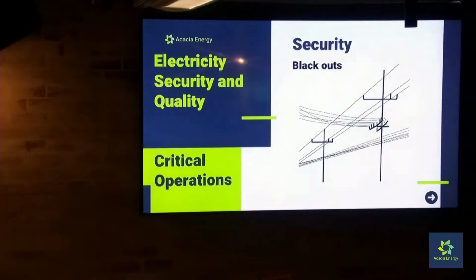So they will momentarily remove power from the network to try and clear the fault. That recloser operation is about 10 seconds, so they'll open for 10 seconds. Hopefully that branch has fallen down off the lines and they'll reclose. If they're able to reclose and power stays on and there's no longer a voltage dip, that recloser will remain on. You'll only have your 10-second outage.